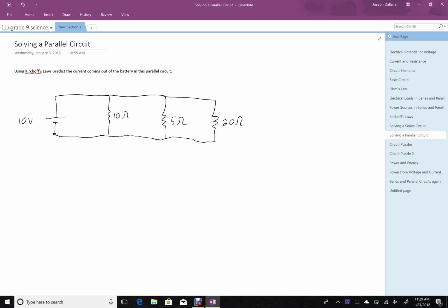So if I consider a closed loop around the circuit, I can go up here, and down here. And what I can see then, if I'm going to call this resistor 1, is that if I go up 10 volts here, I have to get back down the same amount by going just through this one resistor. So this resistor actually is going to have 10 volts down on that one resistor. So here, up 10 steps, down 10 steps gets me back to the original location.